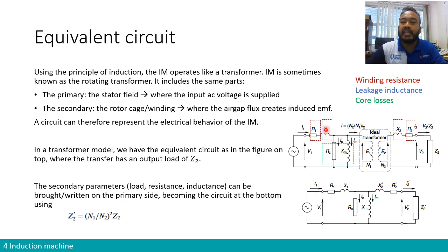So there is a very small amount of leakage inductor in the primary and a small amount of leakage inductor in the secondary. So the leakage, as we discussed in the first chapter, is due to, for example, a certain form or due to the air gap surface. There might be some fringes of flux that leak. So it could be presented as X1 and X2 over here.